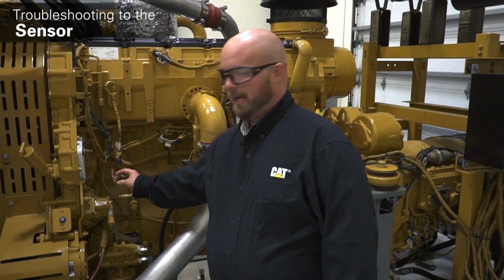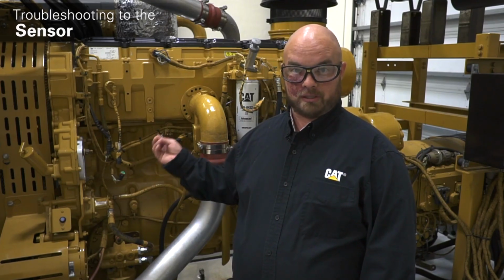Okay, so we've made our open circuit condition out at the end of the harness, and we've checked the active code on CAD-ET. If at this point our -4 code disappeared and our -3 code appears, what does that tell us? Well, when we connected the sensor back up, if our -4 code comes back up again, and when we disconnect it, the -3 code disappears, so every time I plug in my sensor, I get a -4 voltage below normal code. That scenario would tell me that the short circuit I'm searching for is somewhere inside the sensor, and I go ahead and replace my sensor at this point.